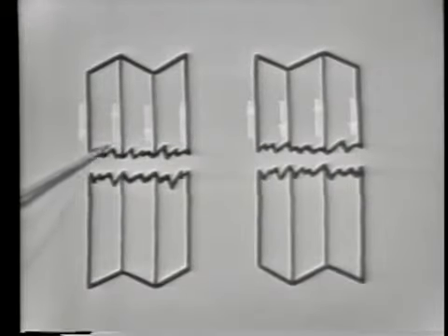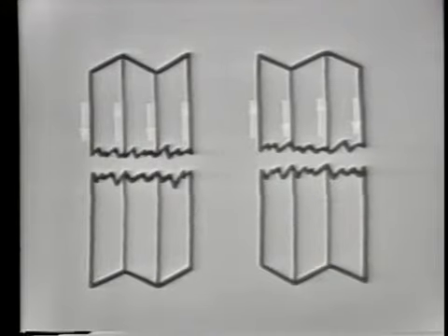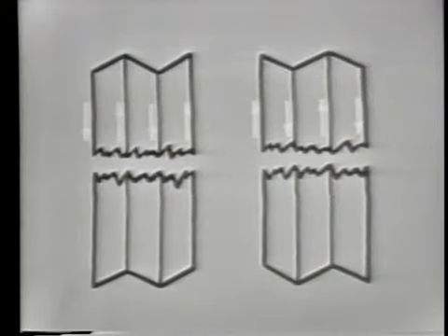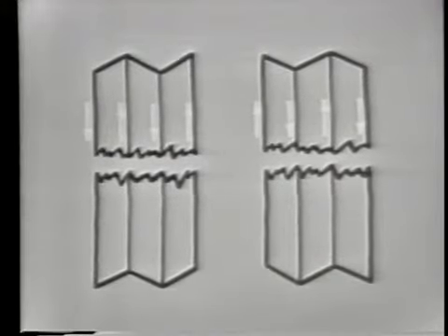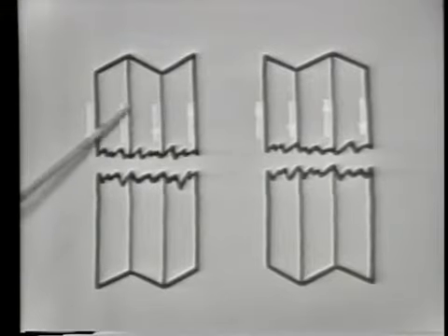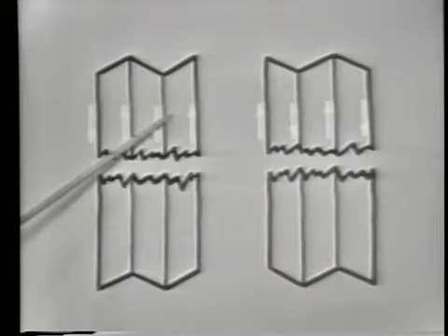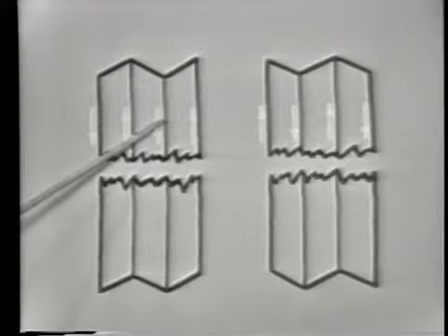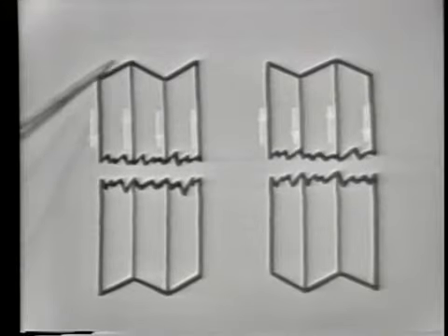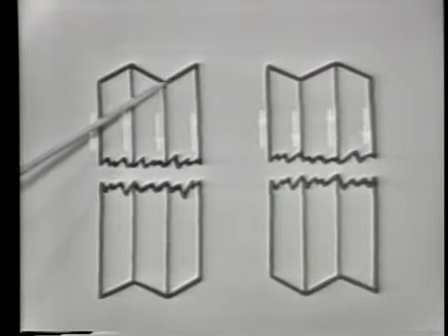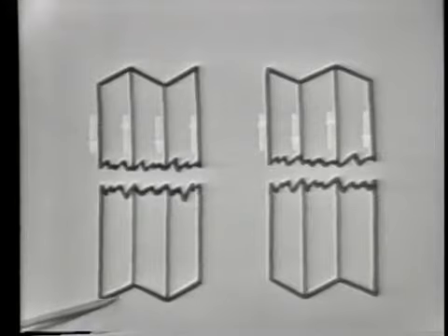Now, here we're representing the crystal when it's made to oscillate in the third overtone. Now, let's notice that the crystal breaks up into 3 layers when it's oscillating at the third overtone. Now, this is representing the deformed layers to produce one alternation.